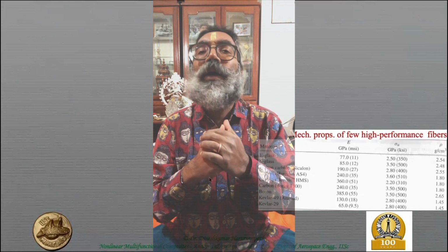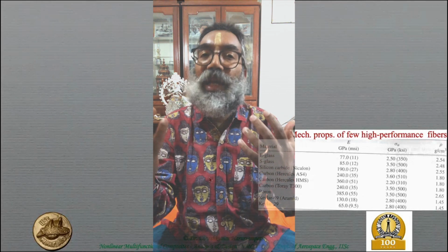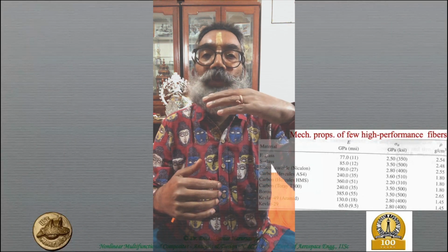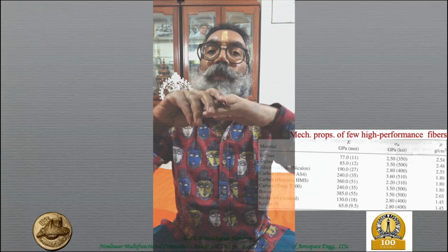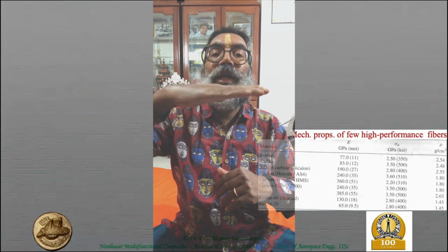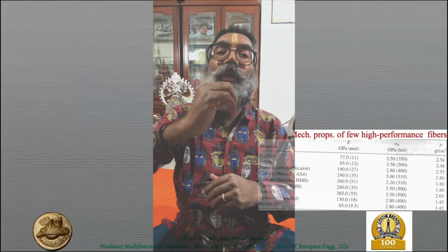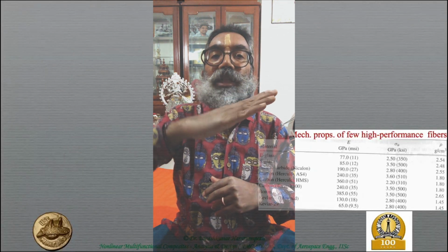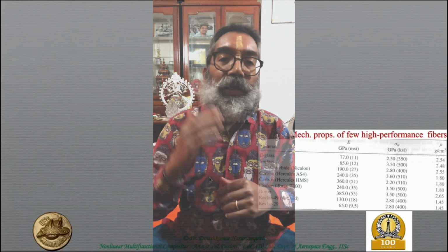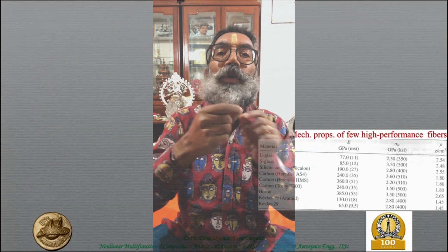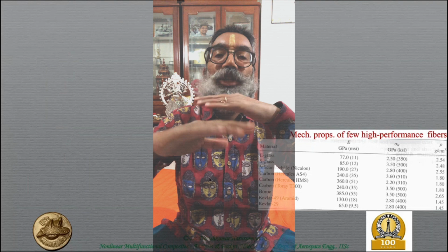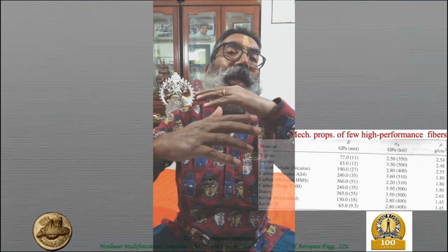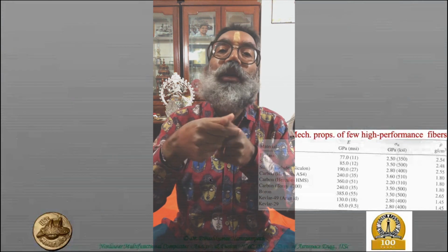It's like between, you would have studied plate theory and membrane theory. A plate is reasonably good at taking bending loads, but a membrane has ideally zero bending stiffness or very, very low bending stiffness, and therefore it's very easy to flex it, right? So it's similar to that we are talking about in a one-dimensional sense. That's a two-dimensional difference between a plate and a membrane. Now we are talking about a fiber and a rod, for example.